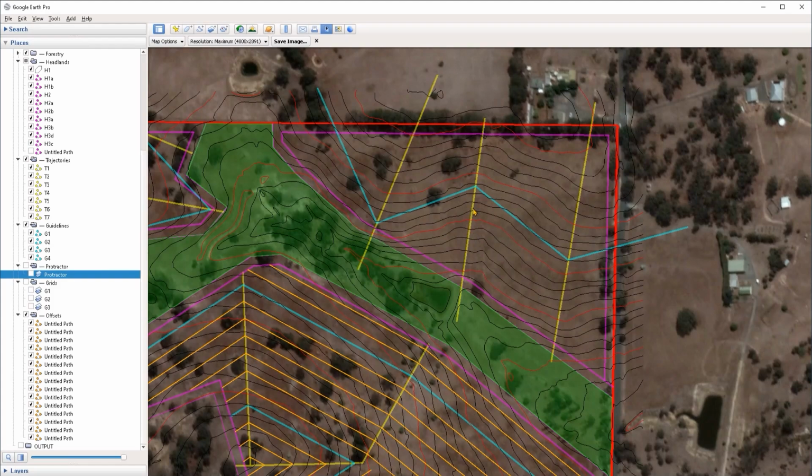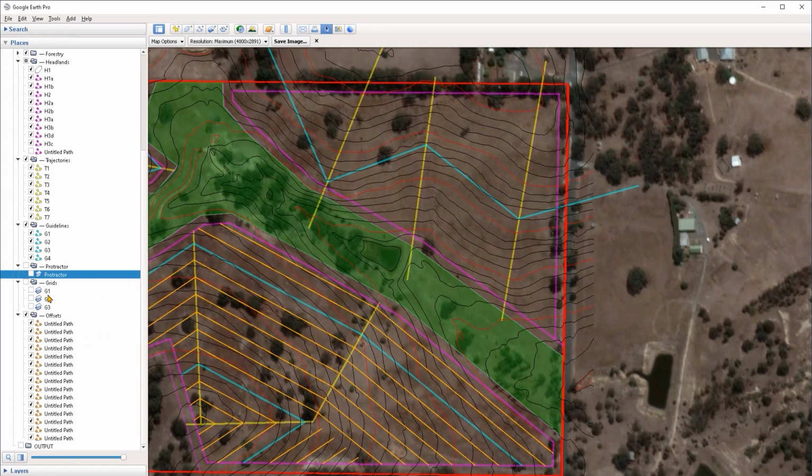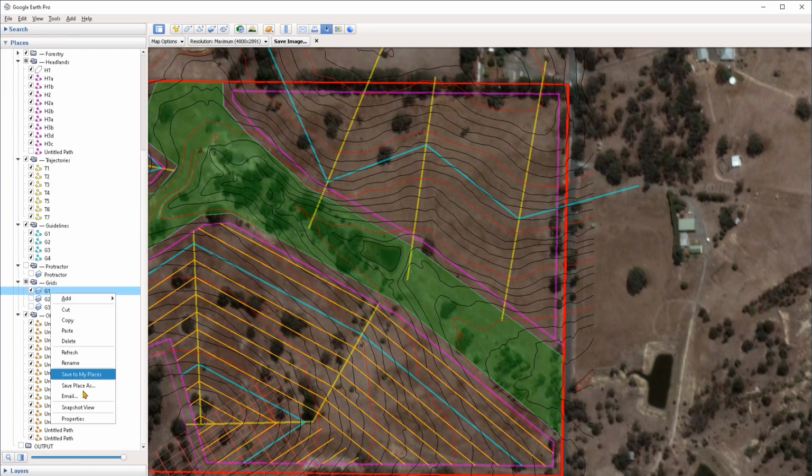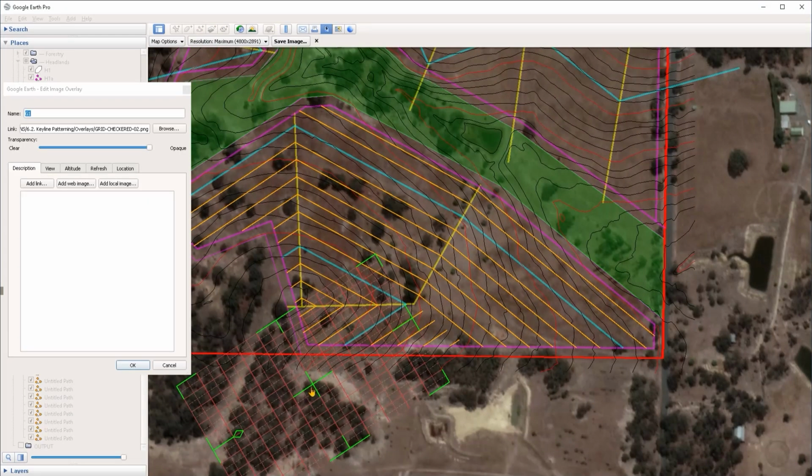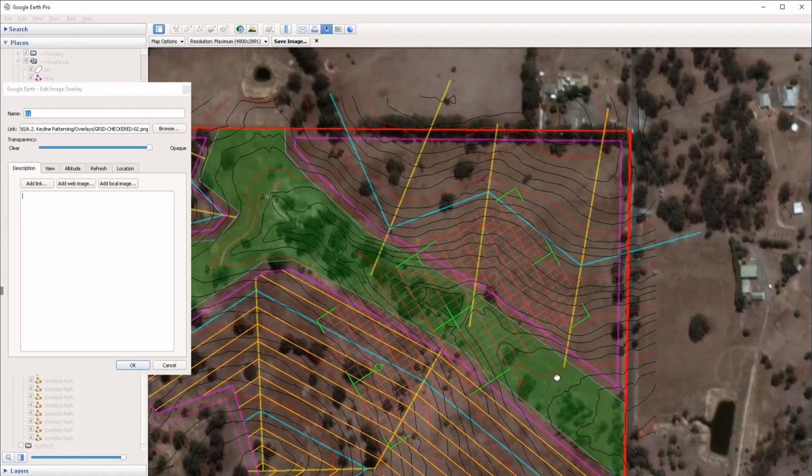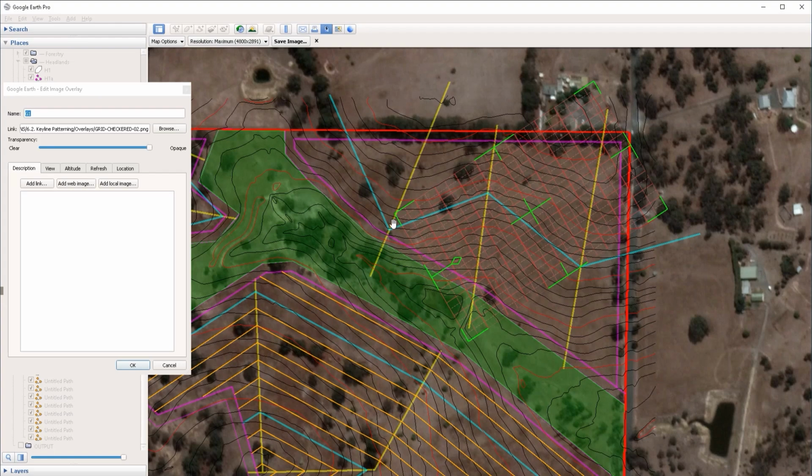So I established the angle split for all of the angle segments of this guideline, so I can just proceed now to overlay the grids and to create the offsets. So I'm going to enable the first grid again. It already keeps to the 15-meter interval that we created for it, so I don't have to change anything. I just have to rotate it into place here.